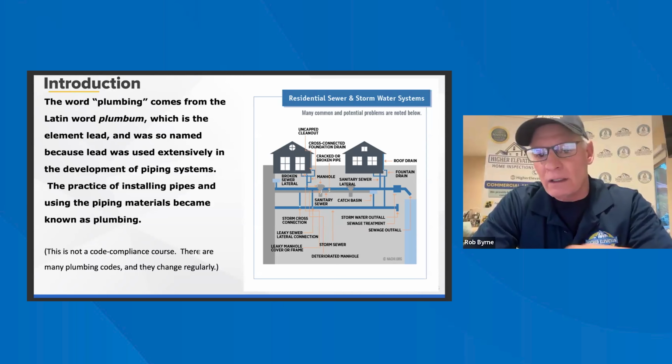Okay, so solvent cement joints are for chemical bonding between the PVC pipes. You'll see the blue primer on it, and then they glue it. So you'll see certain things like that. Solder joint: a solder joint is the most common method of joining copper pipes and tubing. Again, you saw on the slide before that they banned lead in that, so there's no more lead in the solder joints. So it's safer if the water's sitting in there